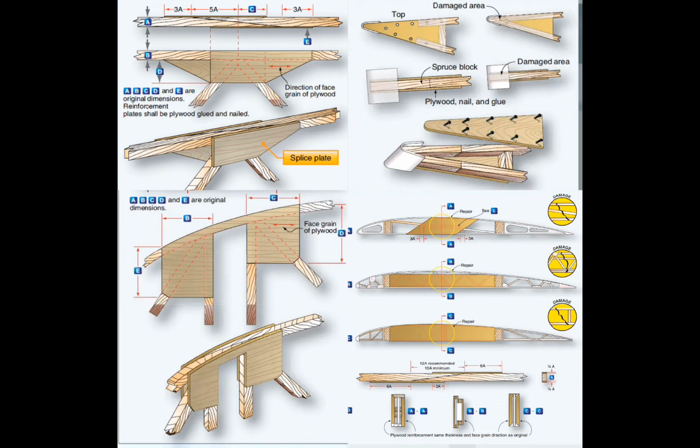What is the difference between laminated wood and plywood? Grain of laminated wood layers are parallel. Grain of plywood layers runs 90° with the adjacent ply. What are two types of glue used for aircraft wood structure repairs? Casein and synthetic resin glue.